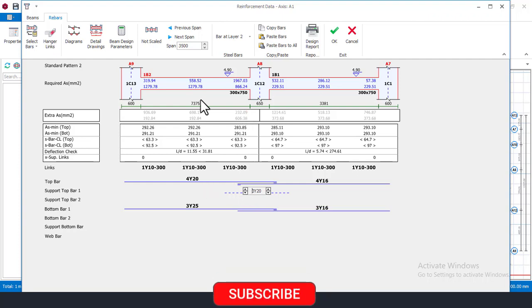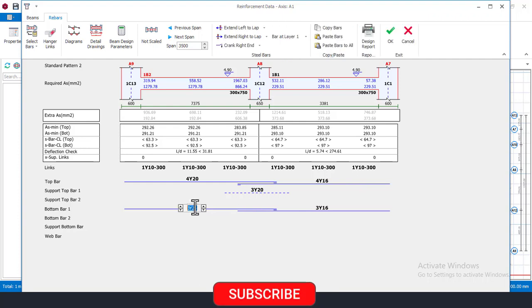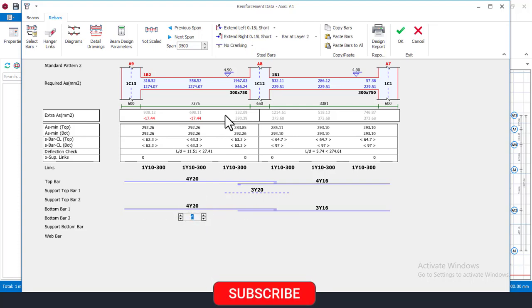So right now, on this 7.37 meters beam, we have 4Y20 first, and at the support here we have 3Y20 at the top. And on this span that has 3.381 meters, we have 4Y16, as you can see. Also at this bottom now, I'll have to decrease this and then increase the number to 4. It's fitting here. I have to try to add a bar here, bottom bar support 2, and then try to increase the number. Let me just try Y16. Yes, it's failing out.